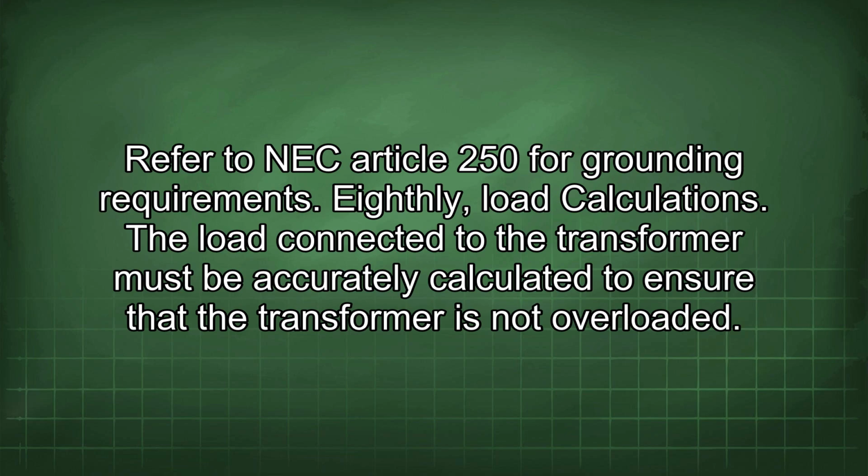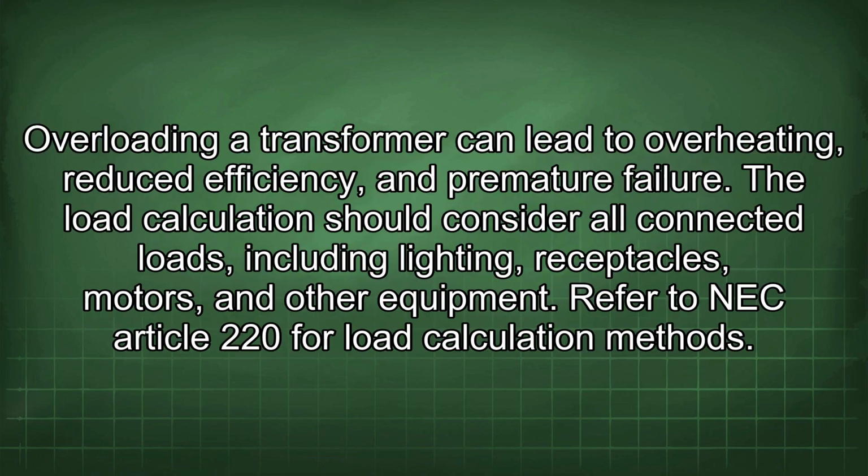Eighthly, load calculations. The load connected to the transformer must be accurately calculated to ensure that the transformer is not overloaded. Overloading a transformer can lead to overheating, reduced efficiency, and premature failure. The load calculation should consider all connected loads, including lighting, receptacles, motors, and other equipment. Refer to NEC Article 220 for load calculation methods.